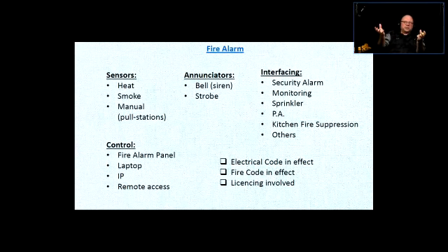So the pressure of the water in those pipes goes down, and that pressure drop is being sensed by the main circuitry of the sprinkler system. And when that is being sensed, the sprinkler system on its own could have a communication circuitry that can communicate with the monitoring station. Or that output of the sprinkler system could be connected to a fire alarm system, or it could be connected to a security system, but usually it's the fire alarm system, right? So that's what I mean by